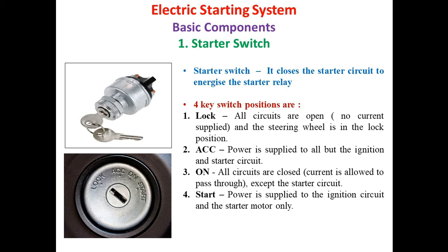Now we will discuss in detail what the electric starting system is. First of all, we will try to understand the basic components of the electric starting system. The very first one is the starter switch. This starter switch closes or makes the starter circuit to energize the starter relay.